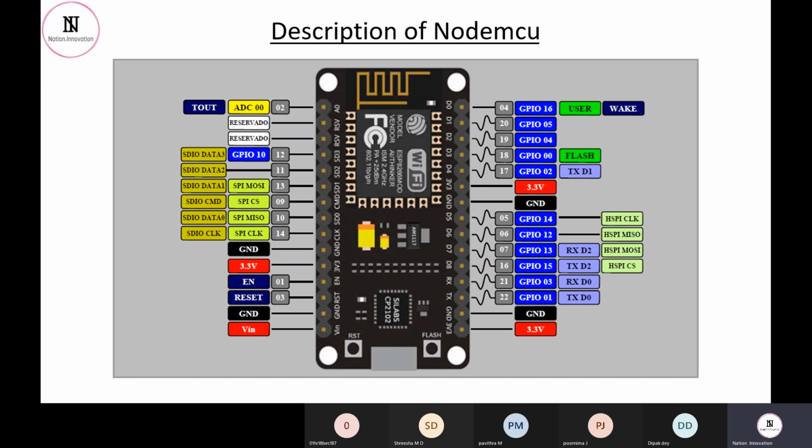Or if a project is very complicated, then I use a Raspberry Pi with that. Why I also prefer to use an Arduino in this case is that there are some sensors which might not be easily interfaced with your NodeMCU board. So if we work with the Arduino Uno, Nano or Mega, and we are able to interface the sensor with the Arduino, we can directly use that Arduino for interfacing. We can send data to the NodeMCU and it will supply the data to the web server, user apps, or wherever we want. Fine. So this is the main thing.